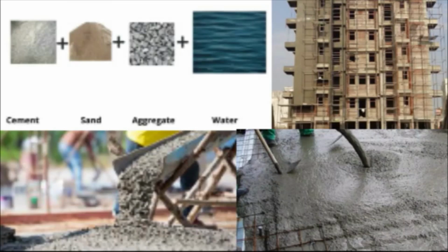The concrete will become hard in a matter of hours, but takes a month to reach its full strength. Therefore, it is usually propped up until that period. During this time, the concrete must be cured or supplied with water on its surface, which it needs for the chemical reactions within to proceed properly.